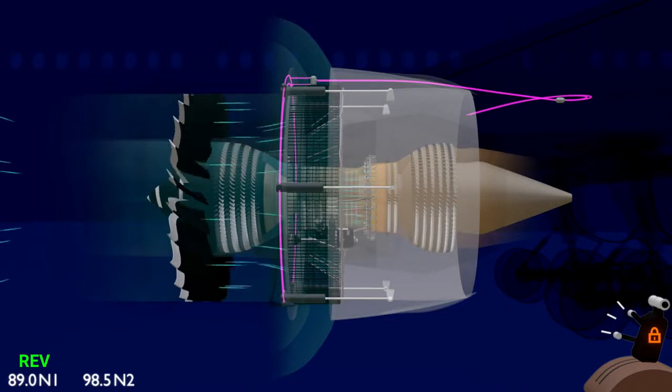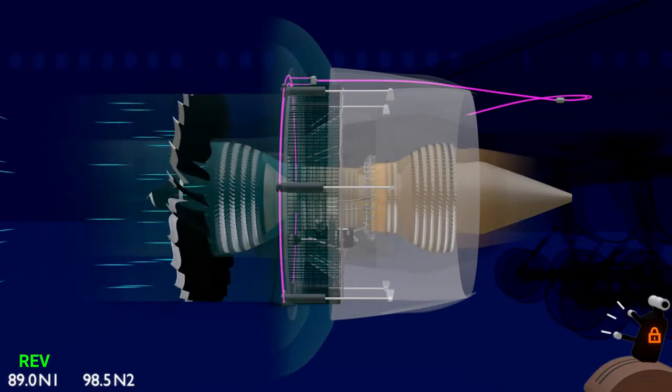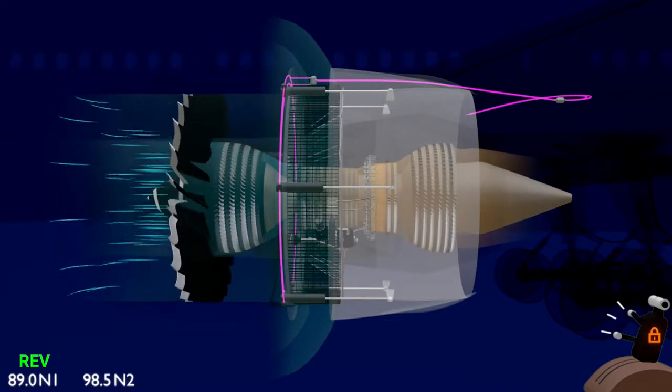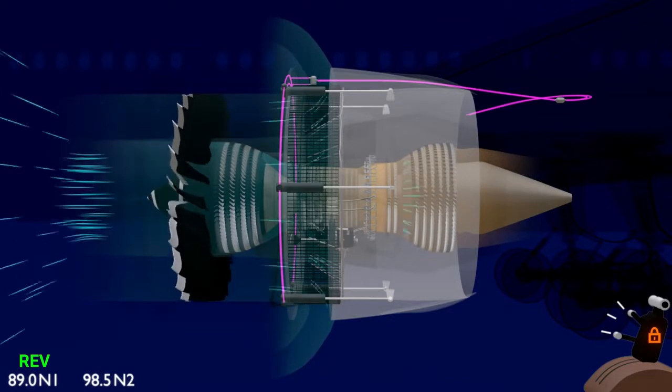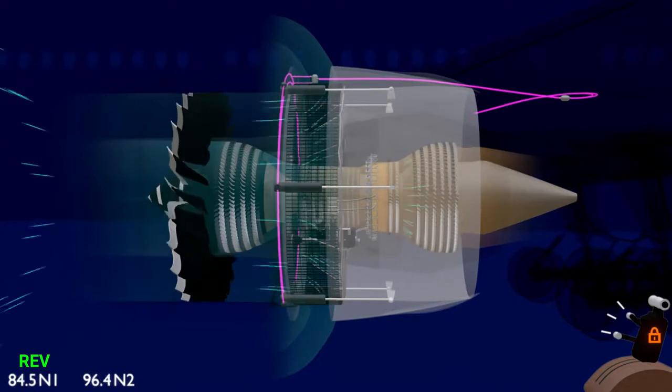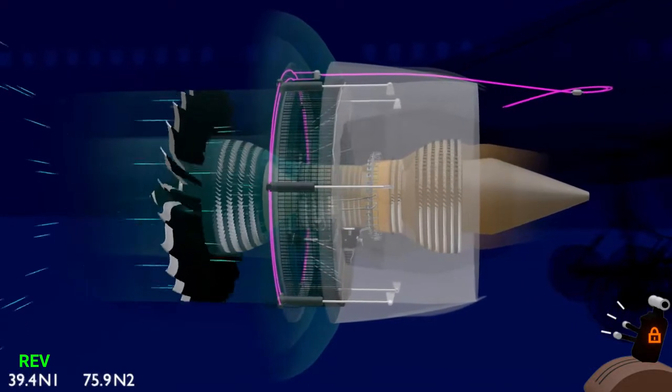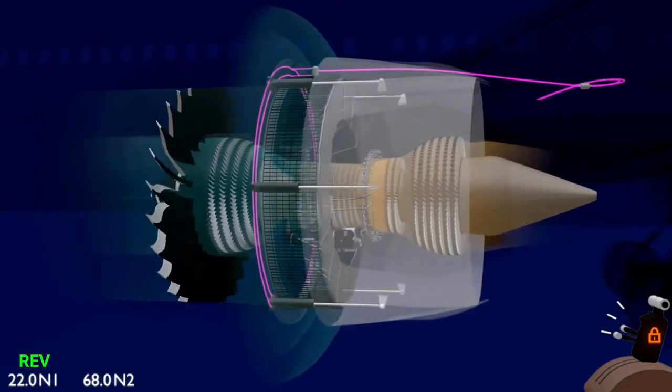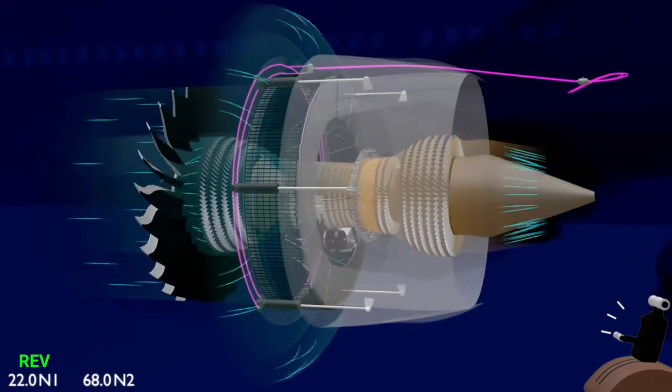Thrust reversers supplement the aircraft braking system in stopping the aircraft after landing, especially in wet runway conditions. To stow the reverser, the lever has to be moved to reverse idle. After the engine reaches the idle speed, it goes to the stow position.